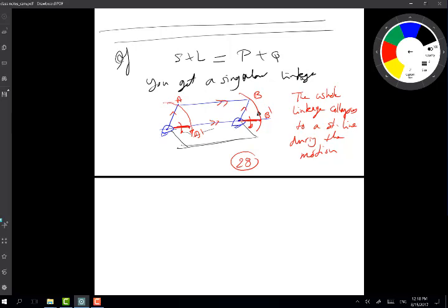So it's not only geometry that's controlling the motion anymore, and hence the singularity. So you get a singular configuration, singular linkage, if you like. Hence, it's better if you do S plus L less than, and then you fall in the safe, assured, geometrically controlled type linkage.